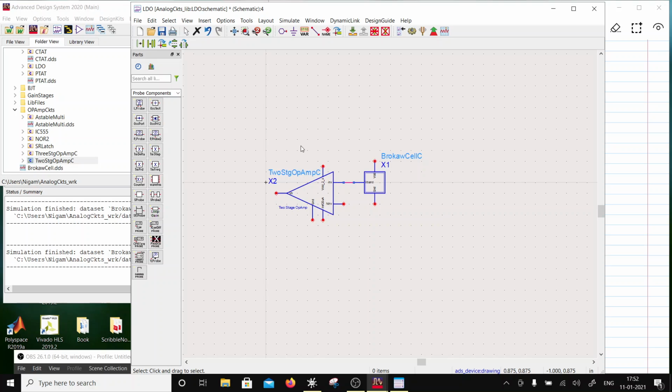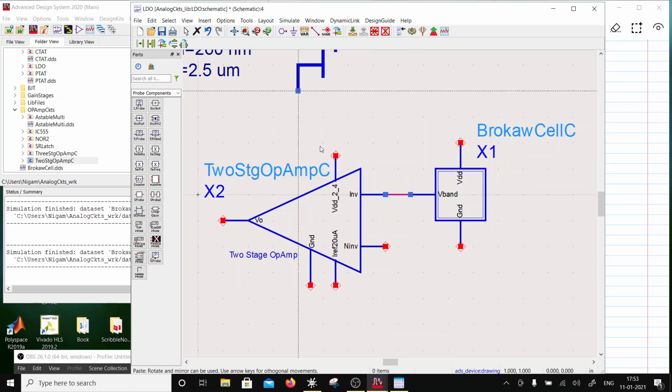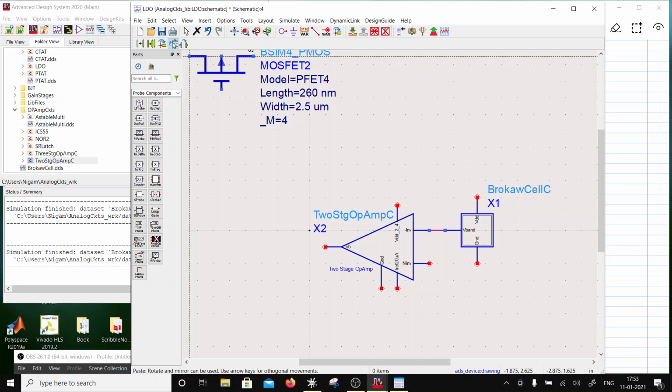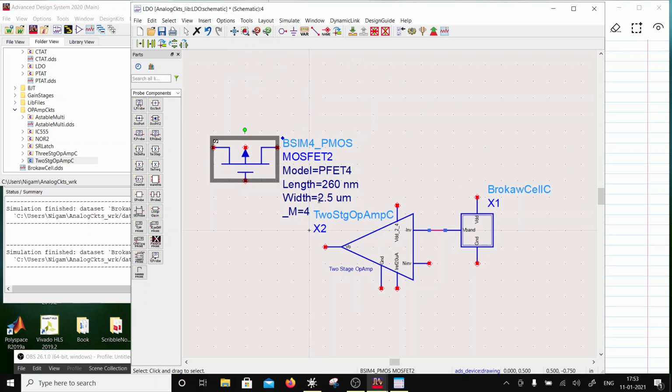Okay, and then I have got a pass transistor. In this case I can go inside and borrow a PMOS device. So let's go inside and pick up this PMOS device, edit, copy, come up in the design hierarchy and say edit, paste, and then I'm going to rotate this. The source has to be always at a known potential. That's what we have discussed till now. I am going to make it 130 nanometer as the gate length, and the width is going to be, let's say, 10. And the number of fingers I'm going to put as 160. So this is a 1600, or 1.6 millimeter, device.